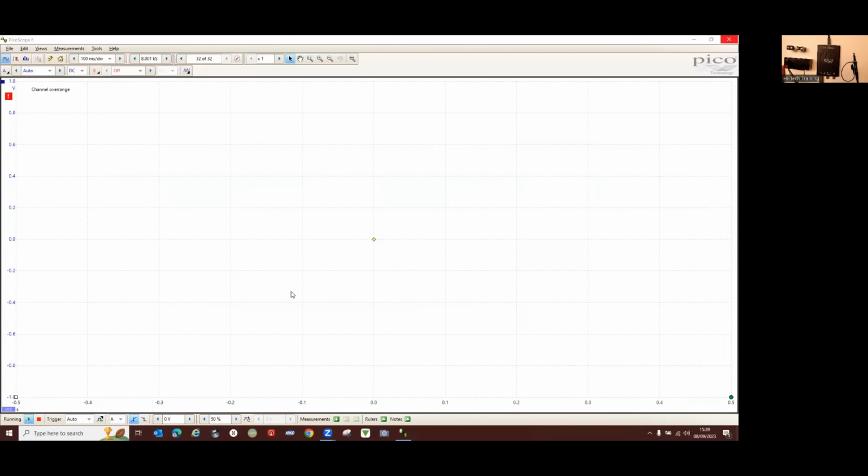there. Okay, so let's come on here now. Things are not going too well. It says channel overage here at present. So we're on the 5 volt, 10 volt. We'll go auto here. So I'm going to go off of auto for a minute. I'm going to go onto the 2 volt range. So we've got 2 volts up here and channel overage because we're looking at 12 volts. And we're giving it around the 2 volt range. So this is an unhappy oscilloscope at present.